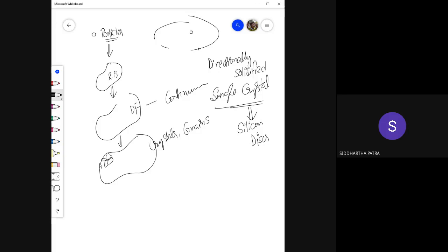Okay. Now, even if we assume that the grains are a single unit quantity, let's say I draw a line across the geometry, and let's say the coordinate along that line is s, and I'm trying to plot any property, let's for the sake of simplicity assume a scalar one, which is density. Now wherever there is a grain, there will be certain variation, but because the grains are in different orientation, they are bound to have something called the grain boundary.